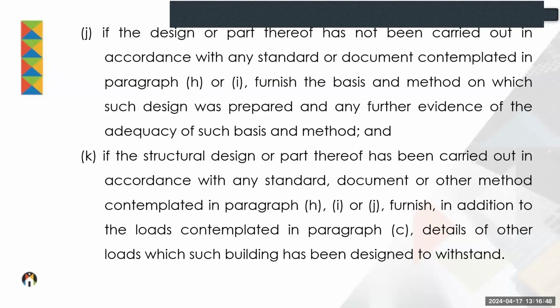Especially where a design has not been carried out in accordance with any standard or document, in other words, where it's the result of a rational assessment, like straw bale walls, they can ask for additional information. How do you know that this wall will withstand all these impact loads and wind loads? Those details and calculations then need to be furnished to the local authority.